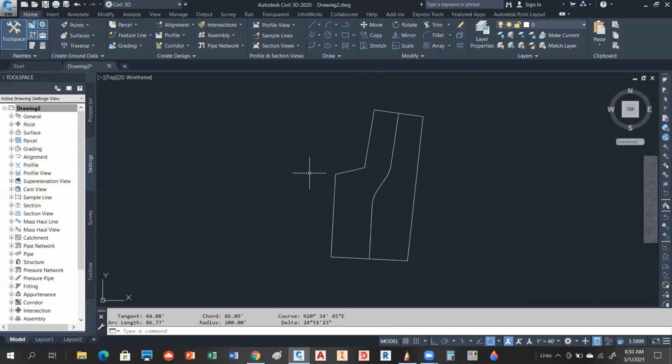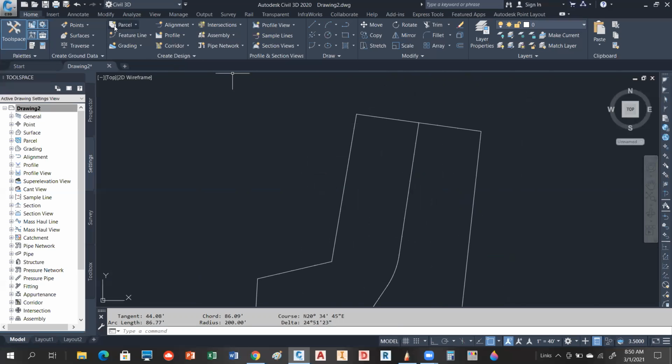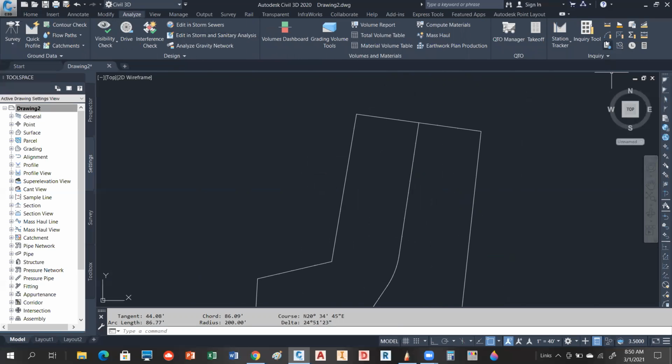And everything should be in here. And just to check this line right here, if we go to Analyze, select that line, we'll notice that my plat shows that as 244.60, and my distance is 344.60. So what's happening is there's an actual 100 feet difference, and the reason being is I'm going to have a cul-de-sac at the end of that 100 feet out. So basically, I'm good.